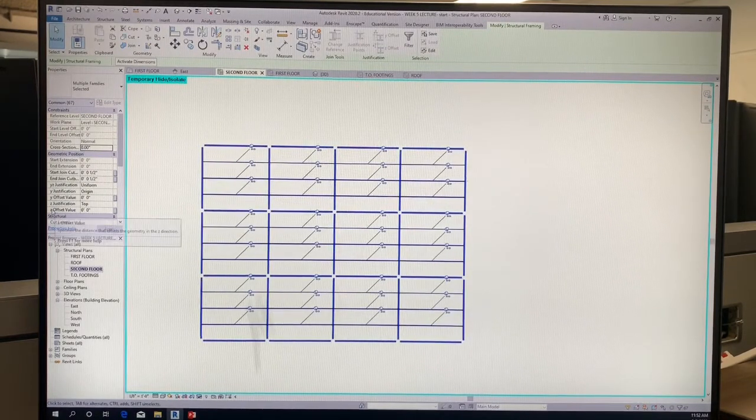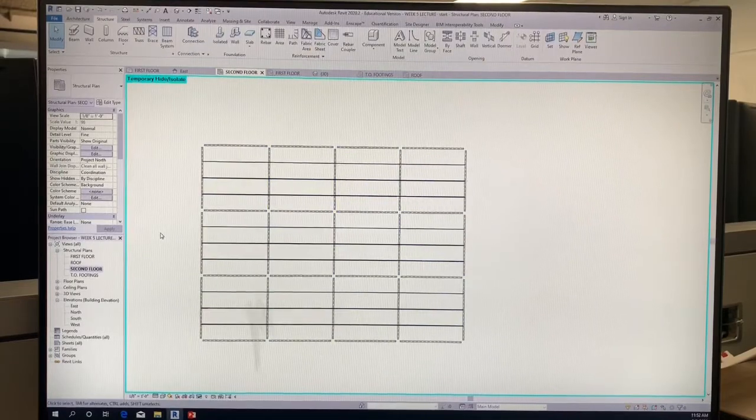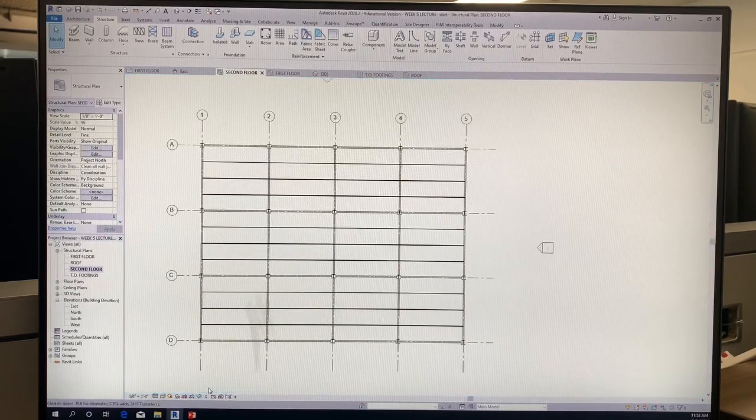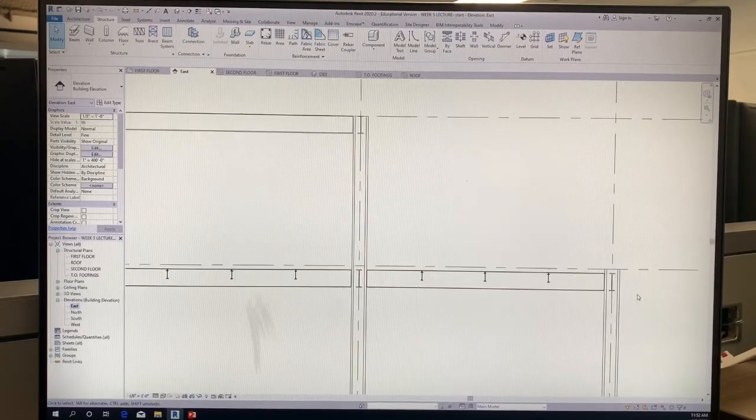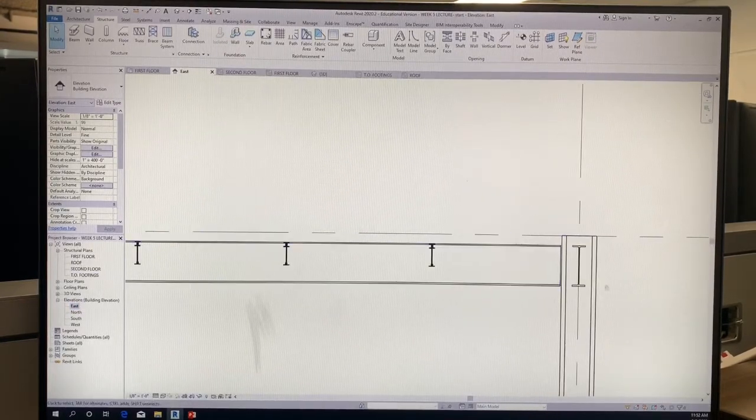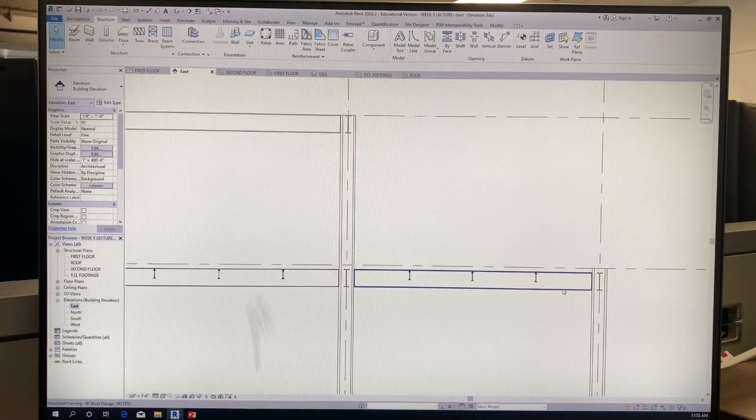And now right here, there it is, Z offset value. Can we please type -5 inches? Again, don't forget the inch symbol. There you go, apply it, or put your mouse on the screen. There we go. Let's reset our temporary height. Now go to your east elevation, and you should now see that we have now left room enough to put our foundation, or our floor slab.